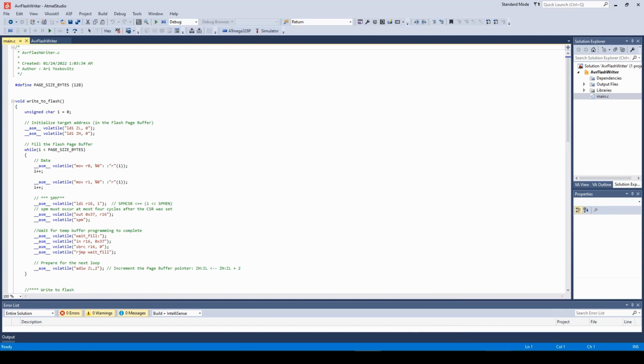So that's where I'm going to locate the bootloader, and I'm going to do that by first assigning this function to a new section. Then I will be able to instruct the linker to locate this function at the address of my desire. Practically, I'm going to add an attribute to the function like that. This directive will put the function in the logical container, which is the bootloader section.